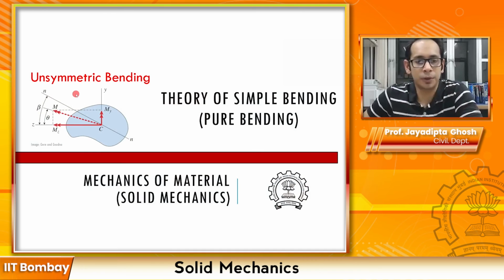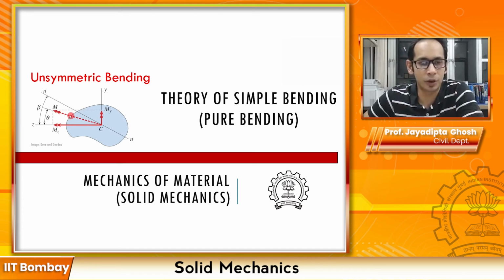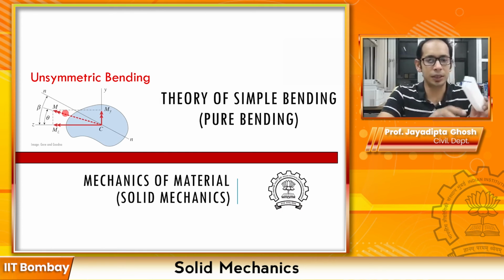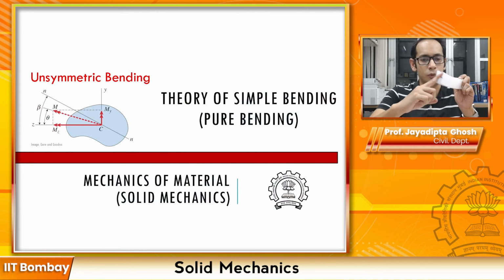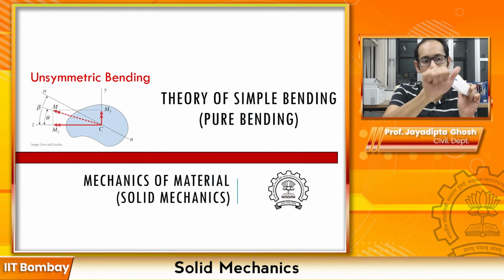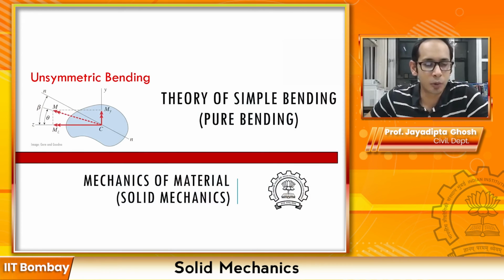Now don't be confused by these double arrows. Moments, like couples and torques, can also be represented by double arrows. All it means is that your thumb points towards that. So the moment I'm bending like this means my moment is pointing towards that. If I am supposed to represent the moment as a straight line instead of the curved arrow we always see, it is a straight line along where my thumb is pointing, with a double arrow. That means I'm trying to bend about this arbitrary axis I'm talking about. So this is what you see over here, that this moment is acting like that.